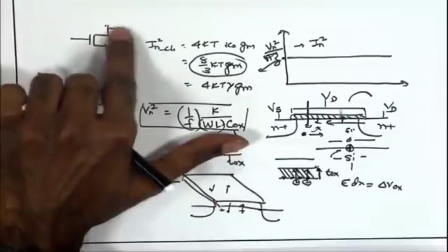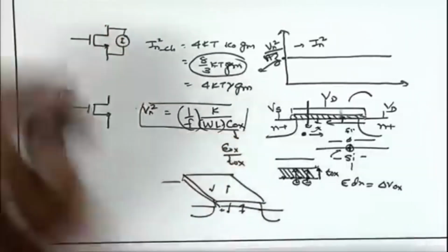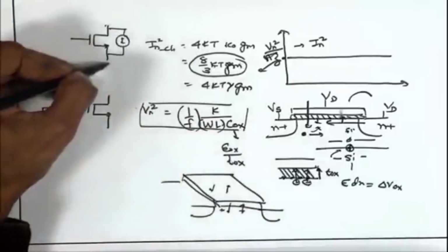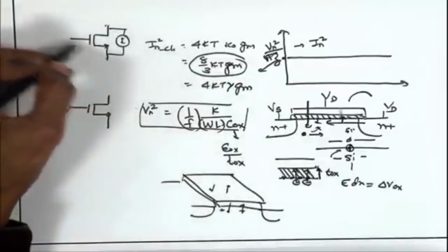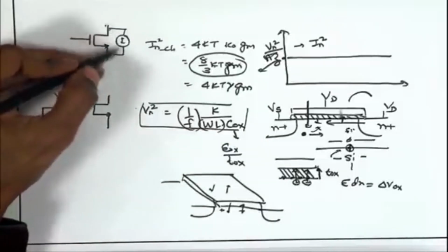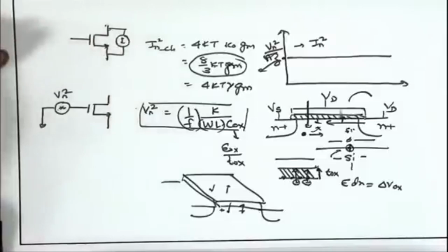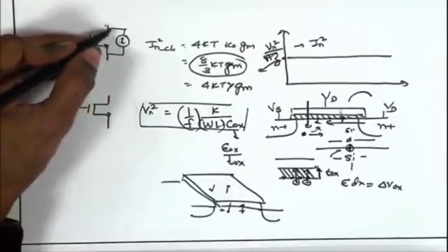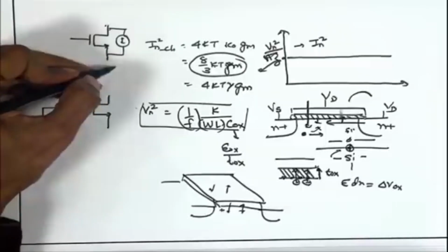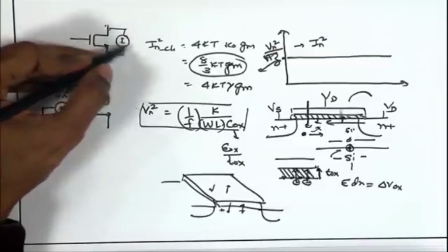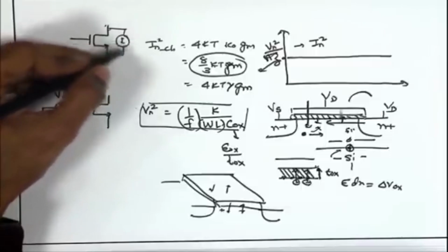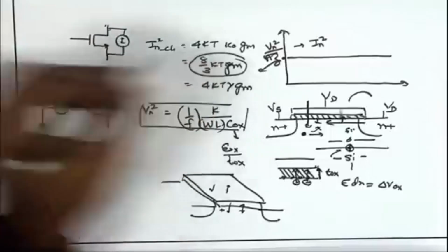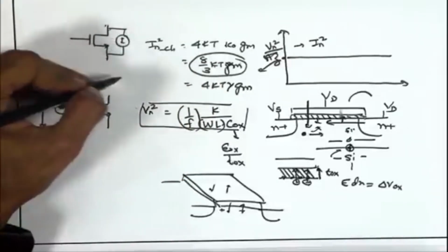So, this is something similar to the gm VGS current that we get from drain to source. In the MOSFET model, we anyway have gm VGS flowing from drain to source. So, for applied gate to source voltage VGS, we have a gm VGS flowing between drain and source, and for a given VGS, the small signal current flowing from drain to source happens to be gm times VGS. Now, I have this noise channel current defined in parallel with the channel conductance, that is 4 kT gamma gm,